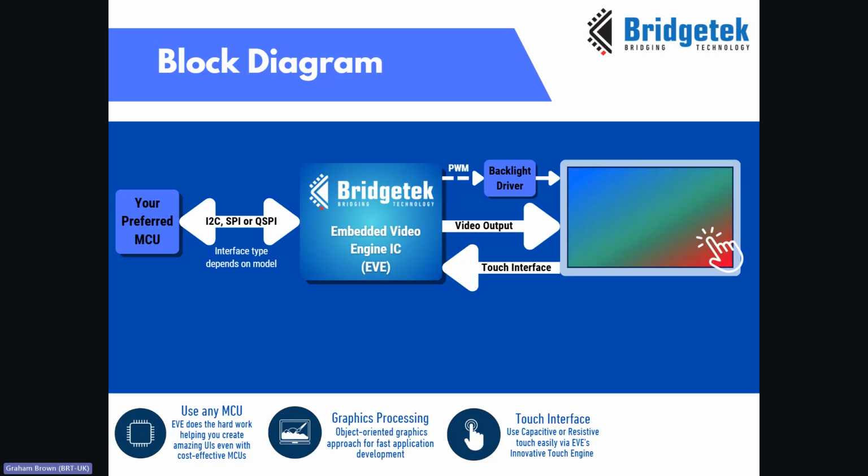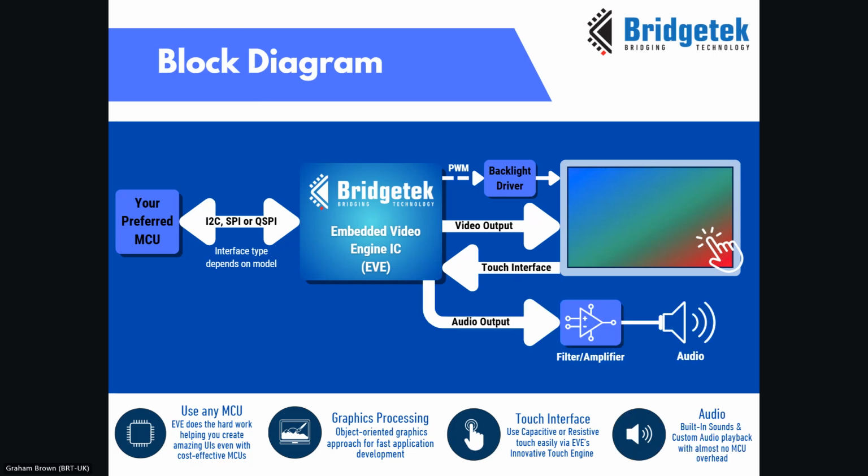object-oriented commands. This also provides a PWM backlight control for the backlight driver on your display, and integrates a touch interface, which utilizes registers in the embedded video engine to indicate when touches are processed on the screen. An audio output is available, which allows you to play inbuilt sounds or custom audio files.